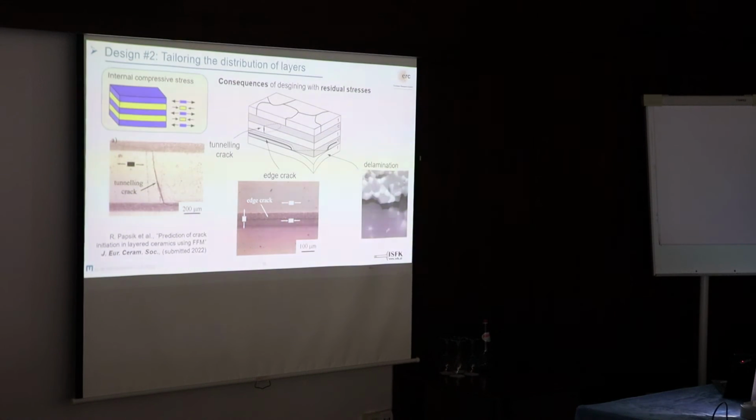Working with residual stresses can be challenging in the sense that if you only deal with compressive residual stresses at the bottom, you get out-of-plane tensile stresses causing edge cracking, and the same applies for tunneling cracks. In this conference, there's one session on finite fracture mechanics. Our colleague Roman Papsi gave a talk on prediction of crack initiation in ceramics using finite fracture mechanics. Using this concept, you can also tailor the layer thicknesses of your material, which will avoid the initiation of this type of cracks.